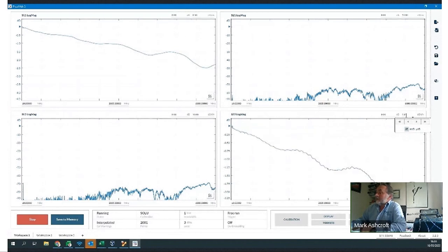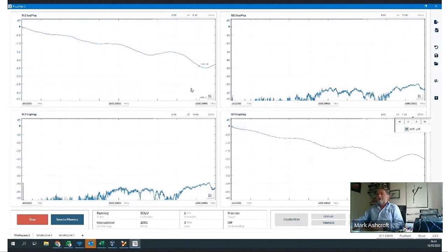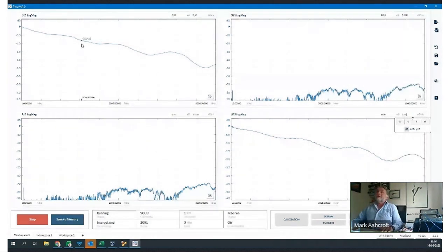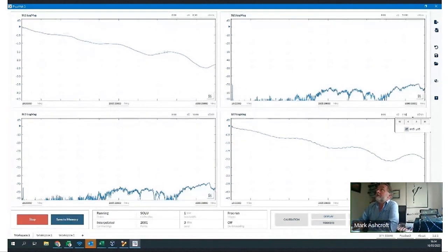On my S11 and S22, I've got a fairly large reflection and some loss along the reflection with increasing frequency. This is a 6 gig span, as you can see. I don't seem to have anything coming through S21 and S12 at the moment. That's more or less noise floor that we see at the bottom there. And that's because this is an open on port 1 and a short on port 2. So not surprising that I don't see any through signal at the moment.